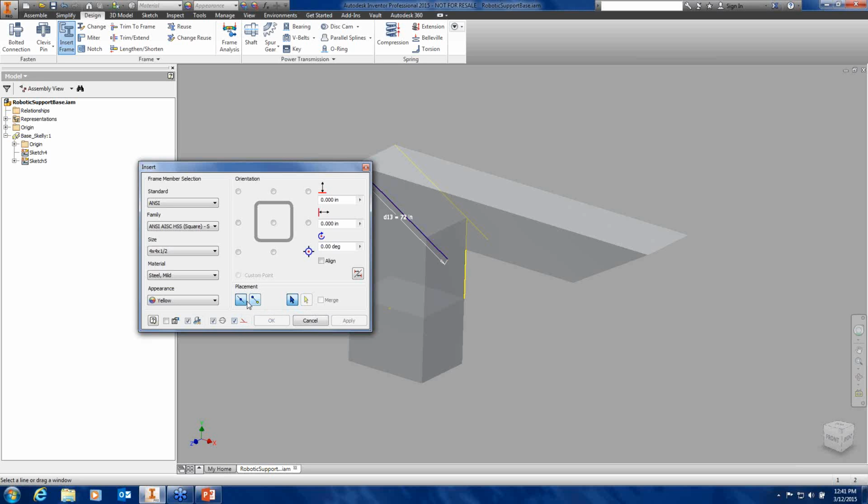line work. On the placement, you've got it by selecting an edge, okay, which is one reason why we have that skeleton in the background there. Otherwise, though, you can pick just between a couple of points and say, let me just insert it there. Of course, everything has an orientation or a justification that you think of in terms of text or orientation, where you could say center justify it, top point, top left, bottom left, etc., as well as some offsets and rotations can be applied to it as well. So you've got various ways of going in there and setting this in place.